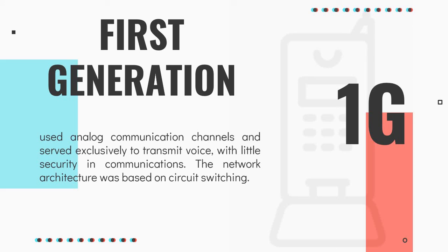It has frequency division multiple access multiplexing and circuit switching on a frequency of 800 to 900 megahertz, and the bandwidth has capacity for 832 duplex channels. Its voice communication is not safe, since it used interoperable radio towers.